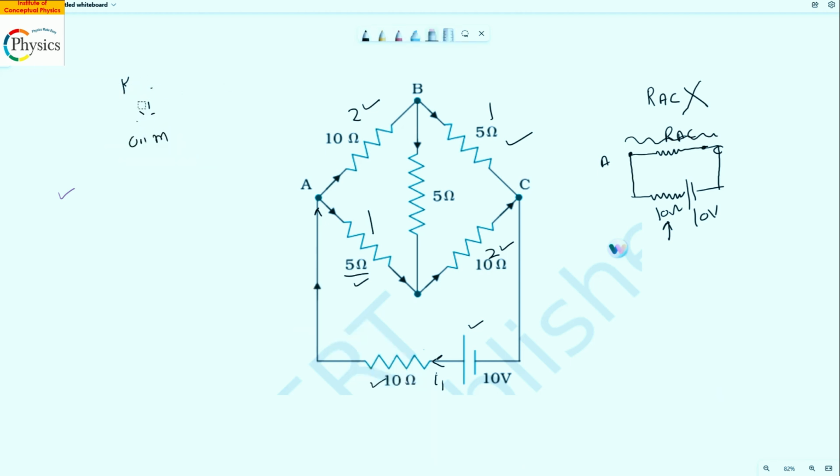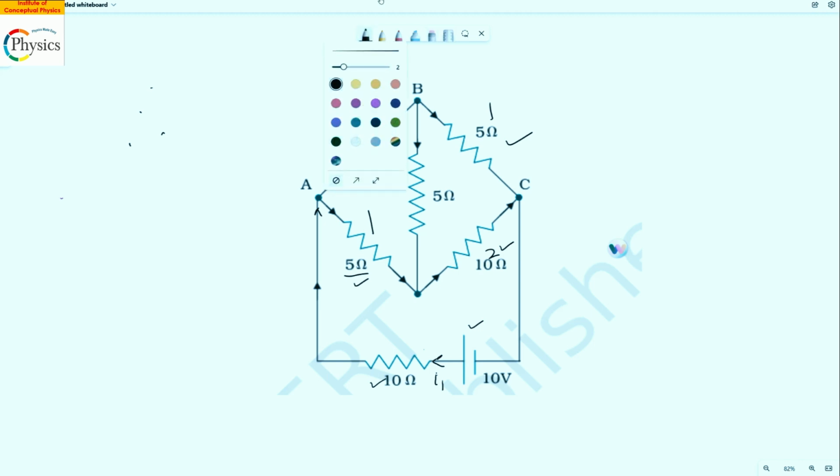All right, let me rub this off and go back to the circuit. The circuit is where you need to pay your attention. I hope this made sense, that it is not easy to solve AC using an effective resistance technique or parallel and series, and therefore complicated circuits get solved only using KCL and KVL.